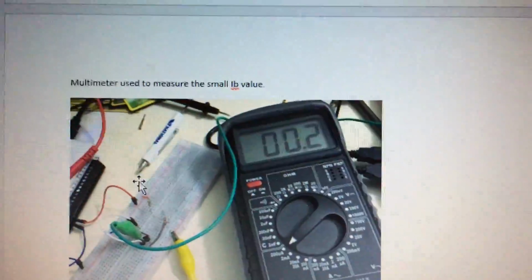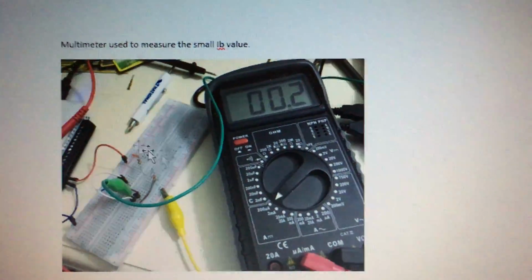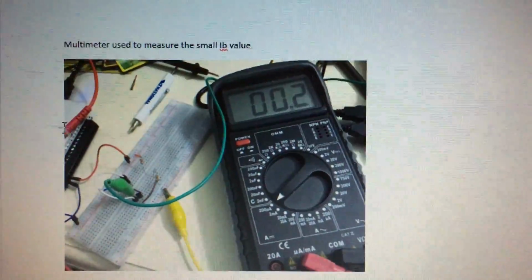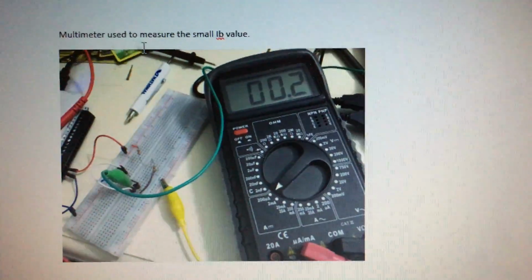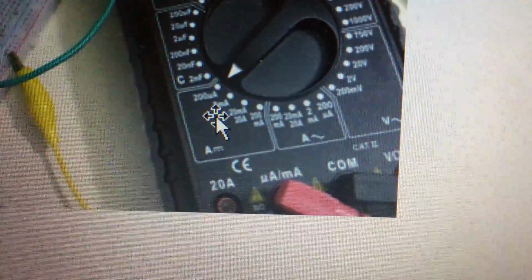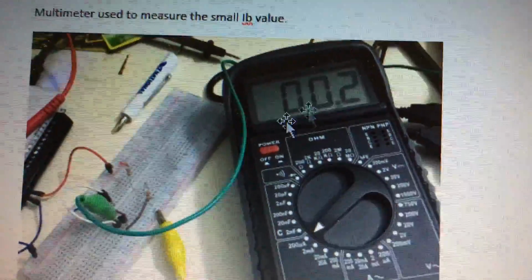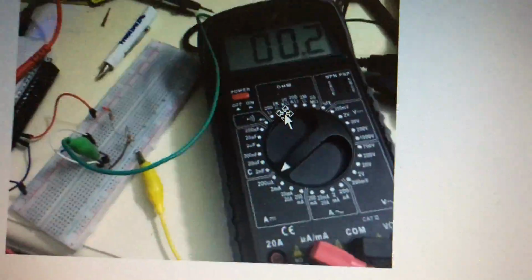And I actually had to use a different multimeter to measure the small base current of the first transistor. You can see it had been set to 200 microamps, just so I could measure this super small value.